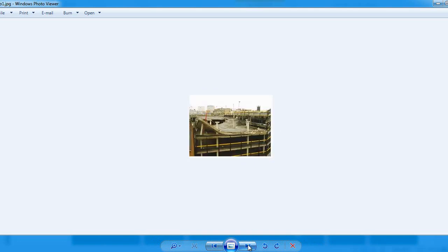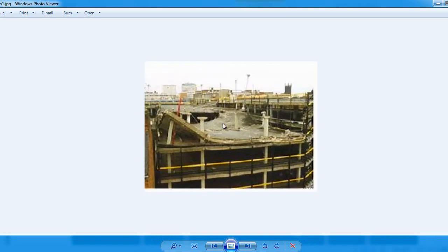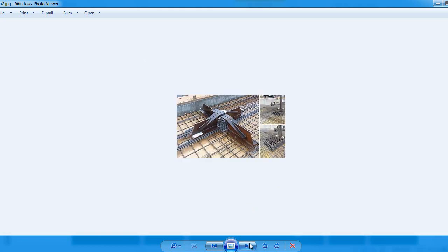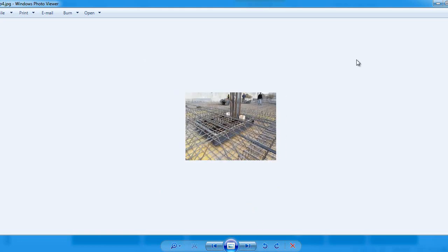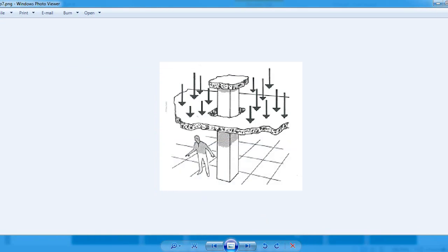Similarly, you see this is a car parking, and heavier drop panels are provided. Why? Because there is a huge amount of punching shear. Similarly, in the failure you see that the slab has moved down. Due to punching shear, the column has a pyramid shape, and the columns are at their own place, they do not move while the slab moves in a downward direction. These are different techniques, inshallah we will discuss them. And let me start the lecture.